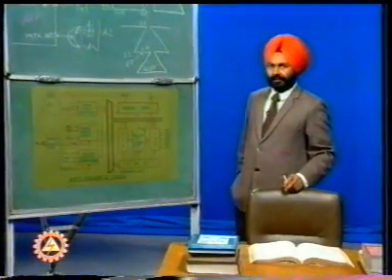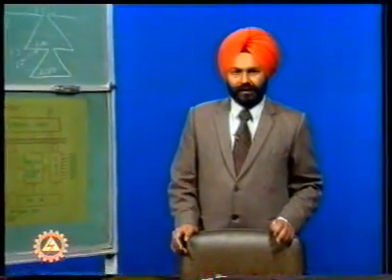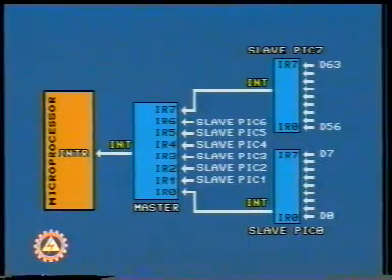We have seen that the interrupt facility can be extended up to 64 interrupts by cascading several such chips in the master slave configuration. When cascaded in the master slave configuration, a maximum of 8 slaves can be configured with the master.